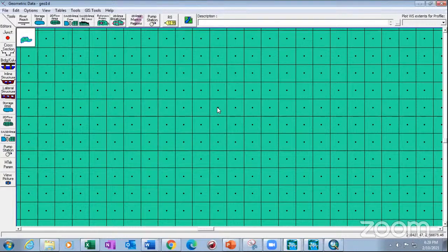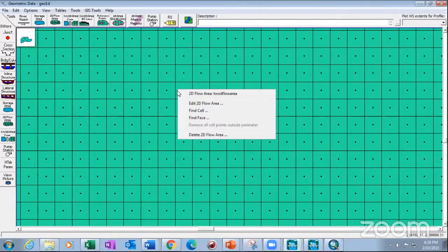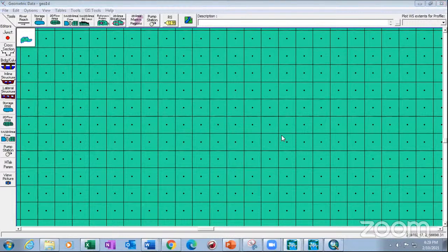I'll explain. From this point to this point, water is traveling. Suppose your dx is so big, say you have given dx as 400 meters, from here to here. For a given computation time, if water doesn't reach from this point to this point, and your grid is again far ahead, in that case you will not converge to the solution. Your solution gets diverged, meaning you will not come to a stable solution, and your numerical solution will have a lot of error.